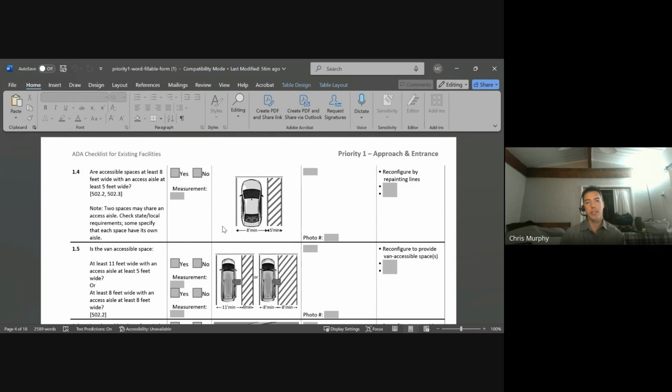So if you're up against a curb, it depends on how that joint looks. If it's just straight to the curb, you can use all the way until the vertical portion of the curb. If there's a drainage dip or anything like that, you'd probably have to stop where it stops being accessible.